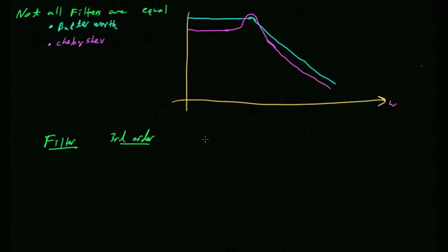All right, so in hertz, that's all right, because that was 100 hertz. I think that's right. That's the same as having a cutoff frequency at 100 hertz, right? If you take 100 multiplied by 2 pi, you get 628 rads per second. And it was a Chebyshev filter? Well, Sallen-Key, okay. Sallen-Key was the style of circuit that I was using to implement my filter.